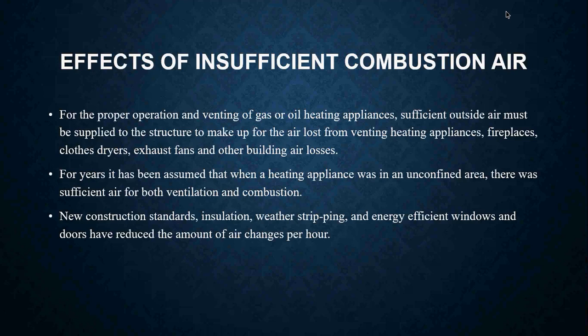Okay, so really the effects of insufficient combustion air are kind of common in some of your units. When we look at a gas or oil appliance, we have to look at the room that this piece of equipment is in. We have to think about where the air that's going to help support your combustion is really coming from.